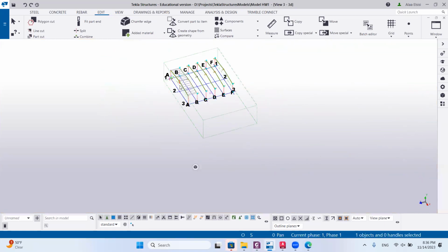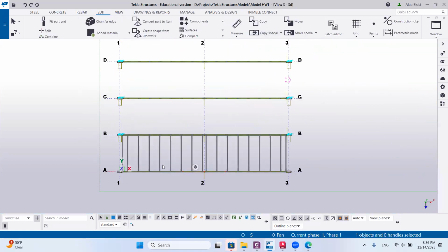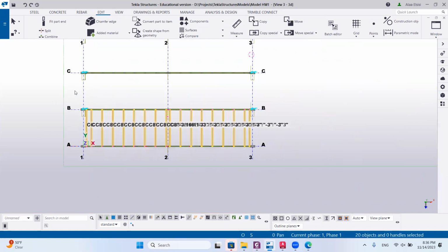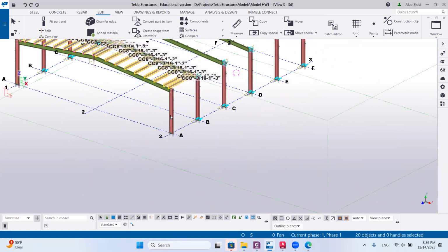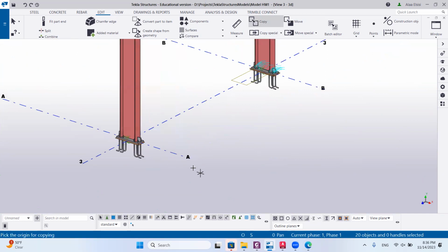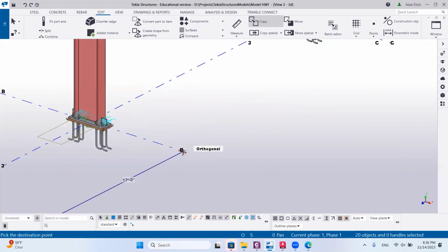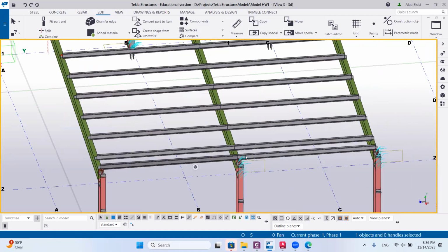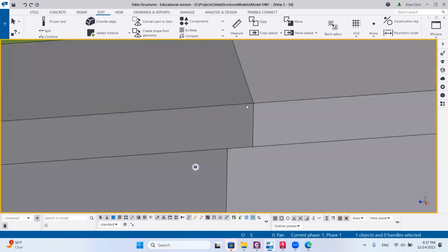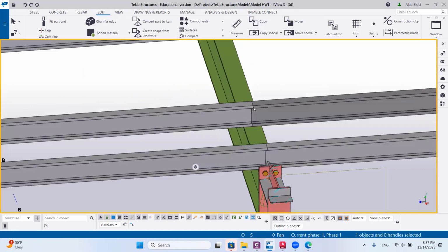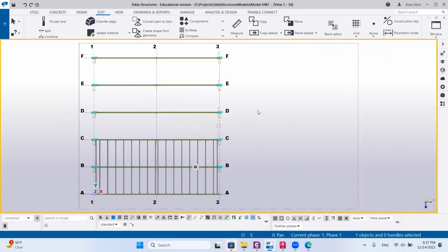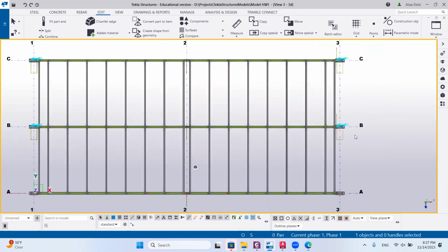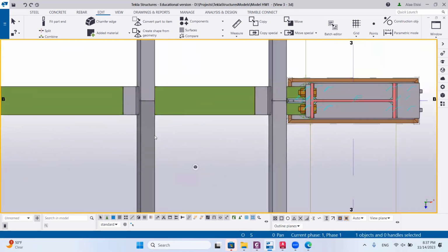Now we can go to this view here and select all the purlins like this and copy them again. So Control C from this point, any reference point, to the other reference point. Okay, good. Look at this, guys, here. It is unacceptable for parts to touch each other like this. This is unacceptable. What should I do? I just need to cut a small part from the side.